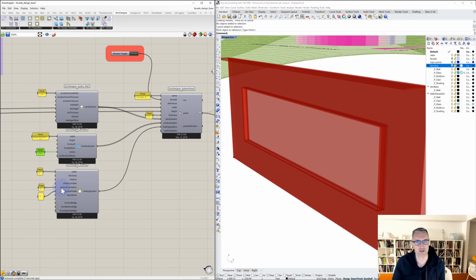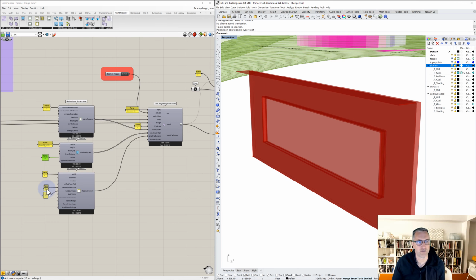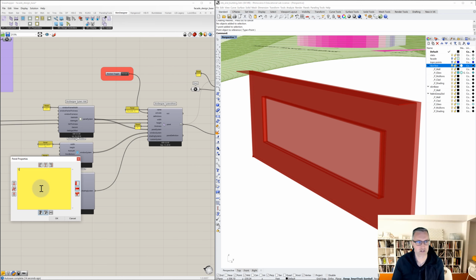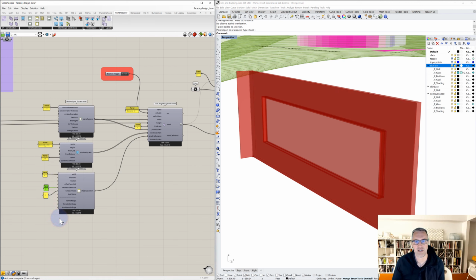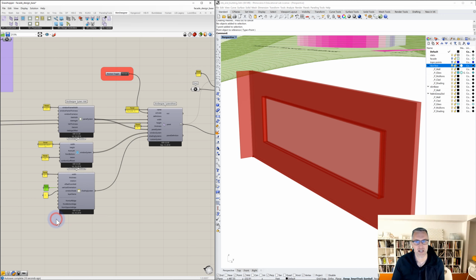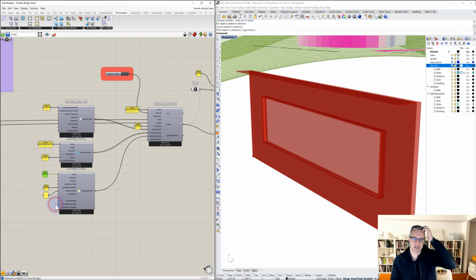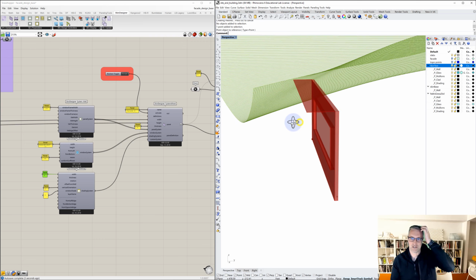So the vertical orientation, if we change that to 1, it will become a vertical shading element. And we can see it's located at the edge of the panel. I want to come back and set that back to 0 for a second and show you the difference, where now the shading element is at the top. If we change the width, maybe we'll go to 4, it'll be twice as deep. So we see that coming out 4 feet.